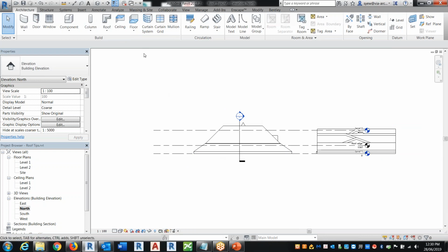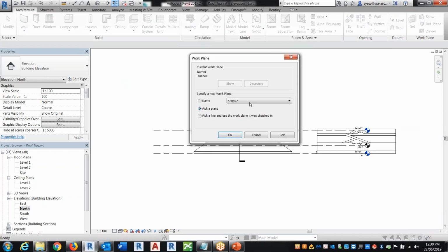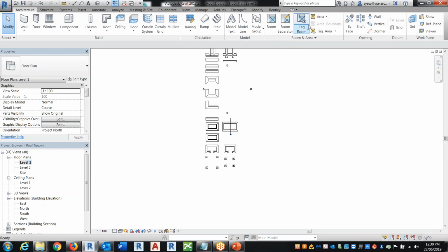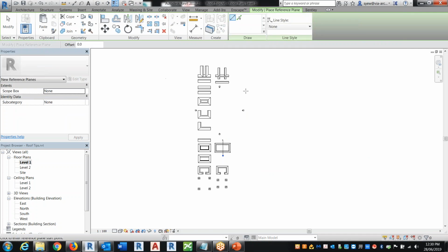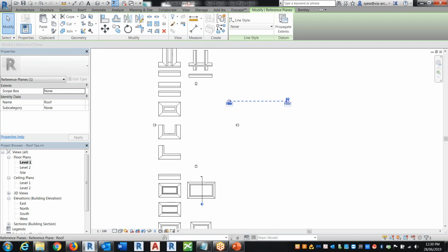Now, just one roof that I always tell users to do is that if you want to do a funky kind of shaped roof, there's always an extrusion. Okay, what extrusion does is that it needs a surface, right? So what I typically recommend users doing is you would set a reference plane. Let's assume that I'm going to put it right here and say this is going to be my roof.